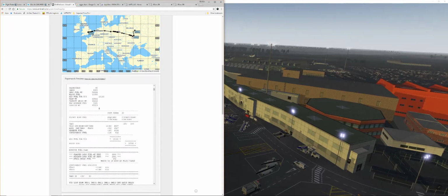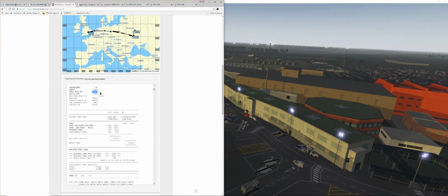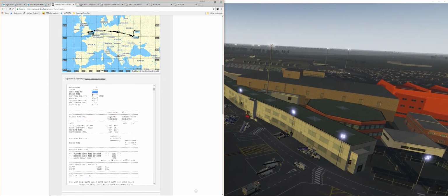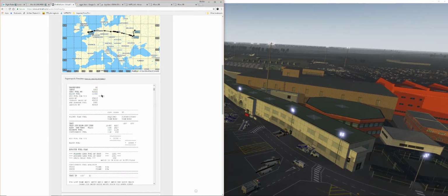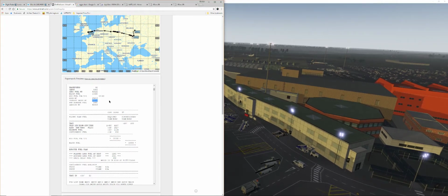And then we have some information for our weight and balance. So we are carrying 80 passengers today, 6.9 tons of cargo. That will give us a zero fuel weight of 59 tons and a block fuel of 10.4 tons, and minimum fuel for takeoff is 10.2 tons. Ramp weight is 69.4 tons. The takeoff weight is 69.2 tons. That's 200 kilograms of taxi fuel.